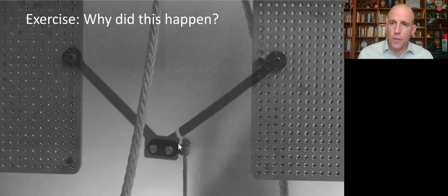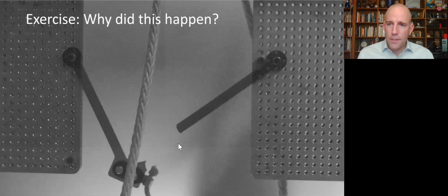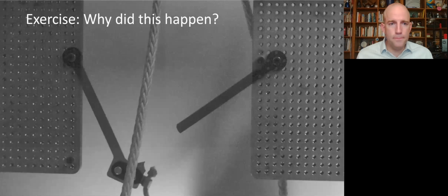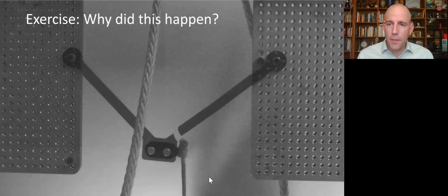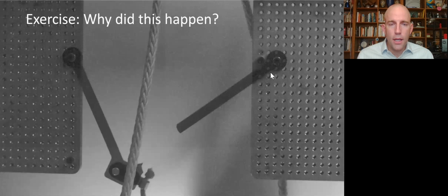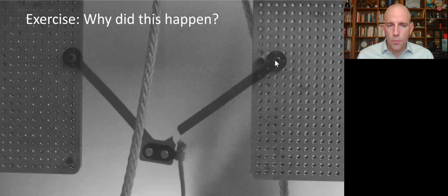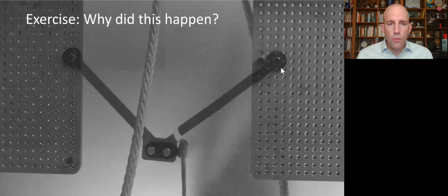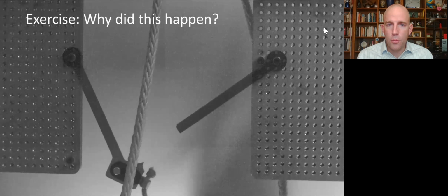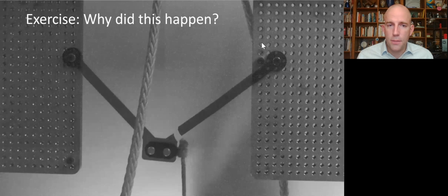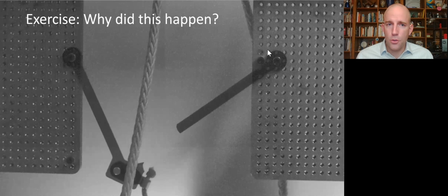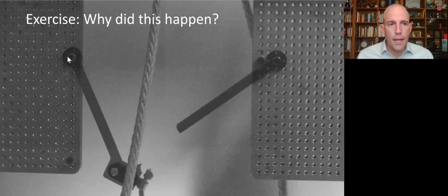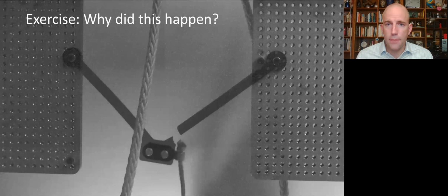And our model of bending stress is sigma equals My over I, where M is highest. As long as we have this uniform cross section, the stress will be highest there. And what does that mean about the loads at these points? Well, it looks like from the shape of the arm, the designer was thinking, oh, these will be axial loads. However, there's probably an axial component, but there must be a component that's orthogonal to the arm in order to get that bending, right? And so we've got an upwards orthogonal component here and a downwards orthogonal component on the left-hand side.